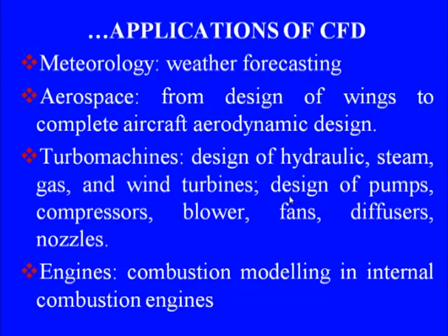Similarly, CFD is also being used extensively in the design of engines. It could be internal combustion engines, or gas turbine engines. For combustion modeling as well as for the flow through a turbo machine, for all these aspects we have numerical simulation models available. For combustion modeling we have to supplement the flow physics with the chemical kinetics of the combustion process. So this is another exciting research area of CFD application.